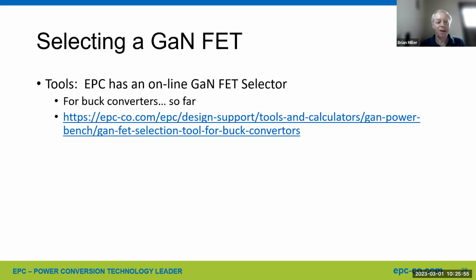Another topic that comes up often is selecting a GaN FET. There's quite a few and how to get started and what to do, because there's conduction loss, switching loss, thermal for the size of the package. But EPC does have an online GaN selector tool. So far it's for buck converters. Here's the link for it. And next page, I'll show a screenshot of it.